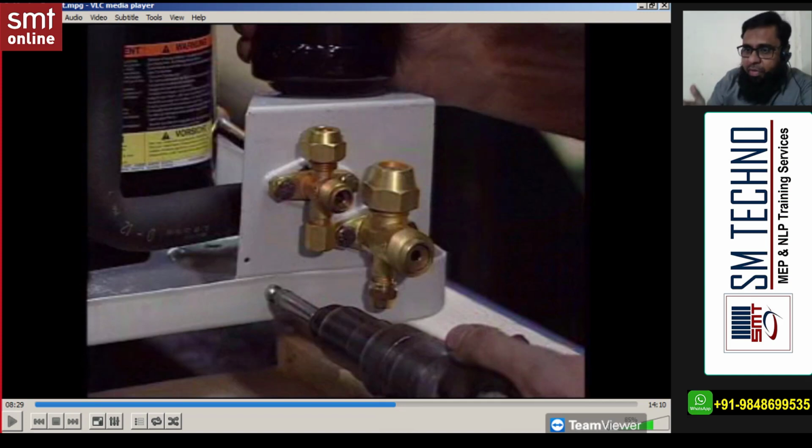Why this difference? When the refrigerant is flowing out from the outdoor, what will be the state of the refrigerant? Liquid or vapor? Liquid, because it has gone through condensation. After condensation, the refrigerant will come out, so the state of the refrigerant coming out of the outdoor is liquid. Then it will be supplied to the indoor expansion, then the evaporator, and change from liquid to vapor, and be sucked back to the outdoor as vapor, right? So one is a liquid line and one is a gas line. Technically we call the gas line the suction line.